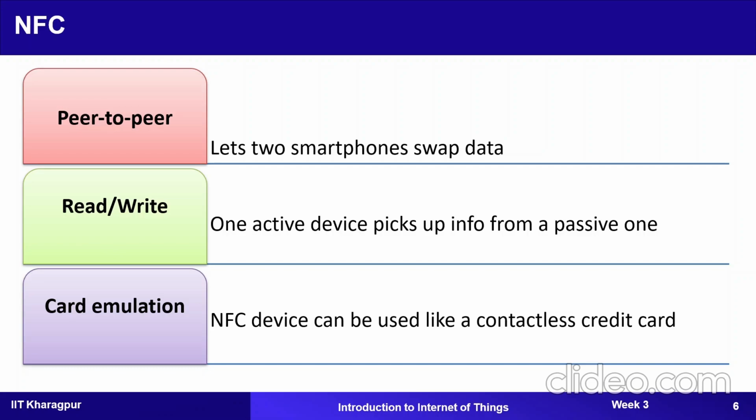It emulates EIA-232 control signals over the Bluetooth baseband layer, that is, serial port emulation. RFCOMM provides a simple reliable data stream to the user, which is similar to TCP, and supports up to 60 simultaneous connections between two Bluetooth devices.